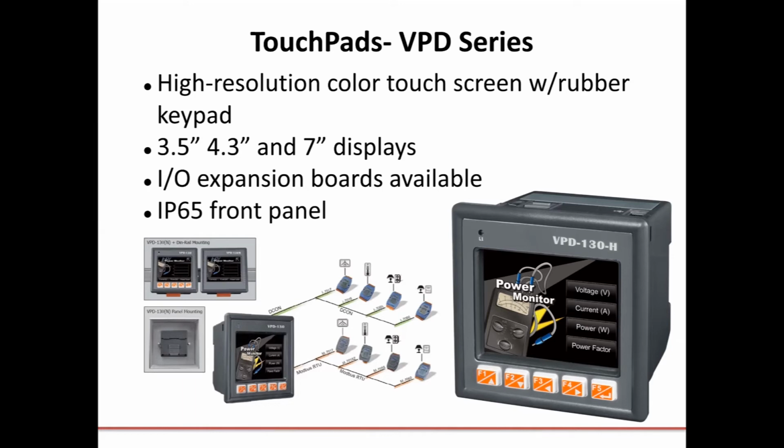The VPD series stands out for its wide variety of communication methods. Its built-in communication ports include RS-232, RS-485, and USB interface that enables integration into the system, allowing users to control, monitor I/O at the remote side, and update firmware directly from a central computer. That's the USB interface. Also, the built-in non-volatile storage makes VPD series more reliable for rugged environments. But again, it is built on a lot of the same components as the TPD series.